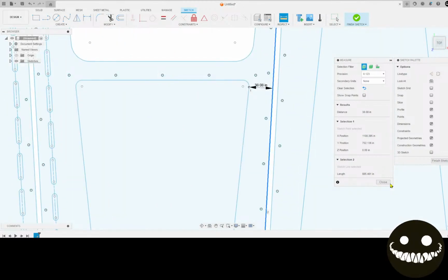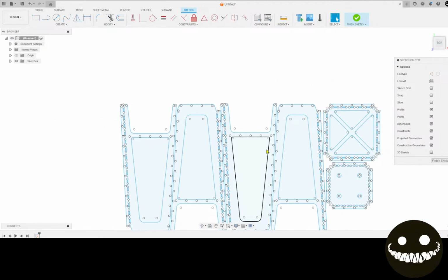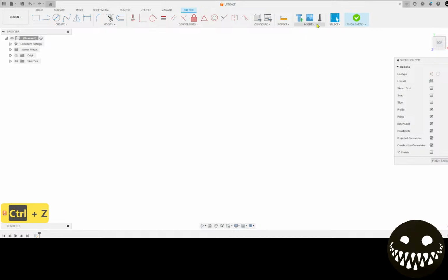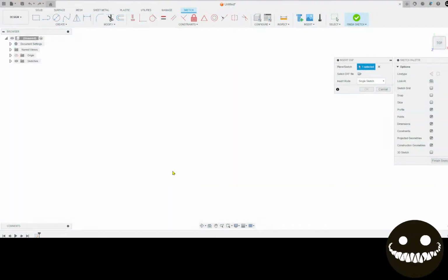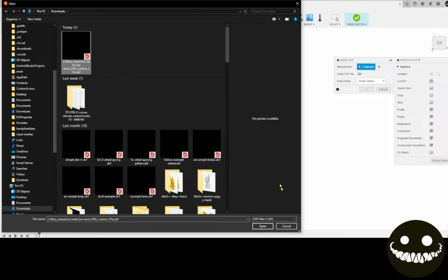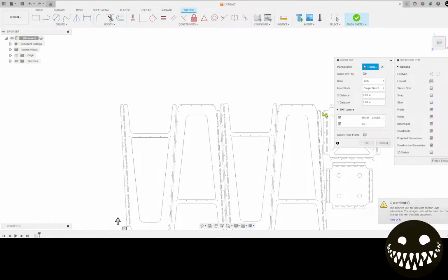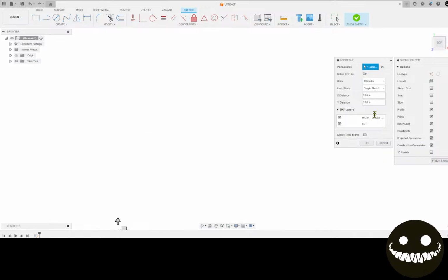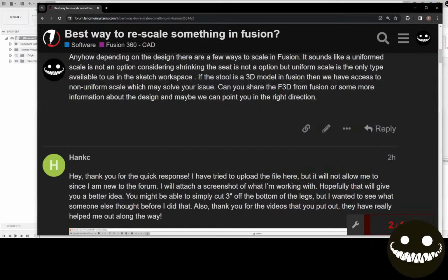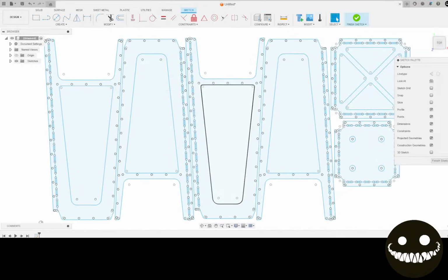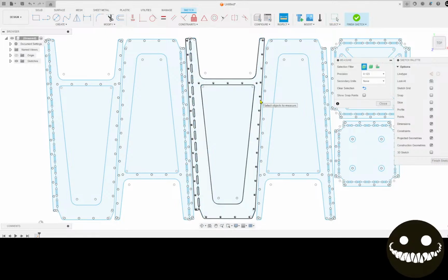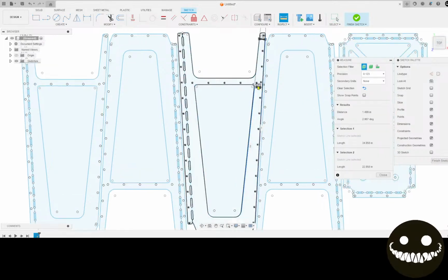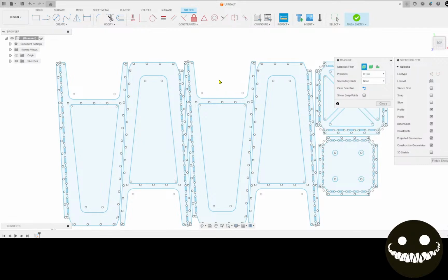So yeah, 38 inches, so it was a metric import, so let's reinsert that. You can just tell by the way it blew up like that. And this time we're going to go to millimeters. Okay. And that's more like 1.5 inches-ish.